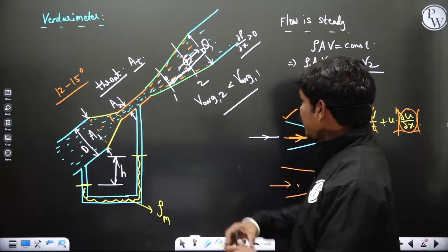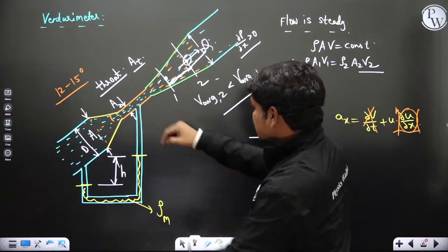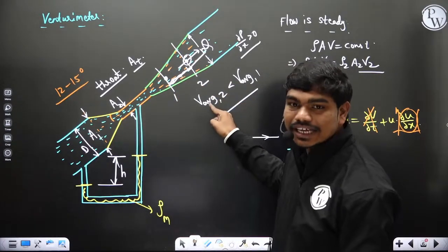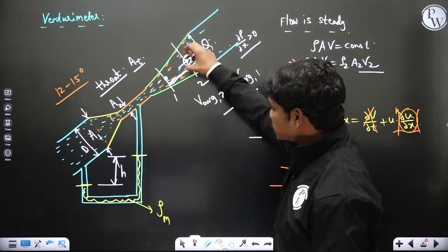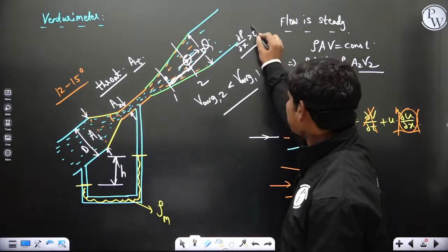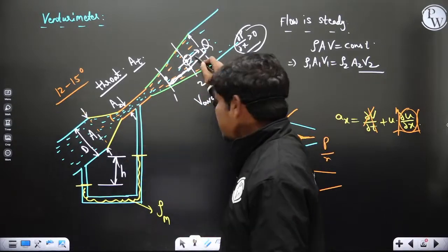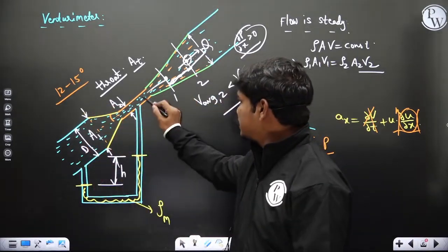But when you keep a higher cone angle here, let us suppose your cone angle is high, and you connect it in the reverse way, then this V average, or the convective deceleration, will be very large, because this acts as a diverging section. If convective deceleration is large, the adverse pressure gradients are also very large in the downstream direction.